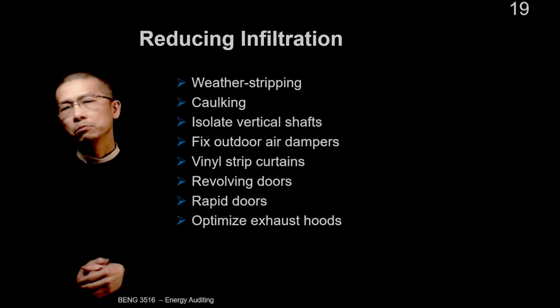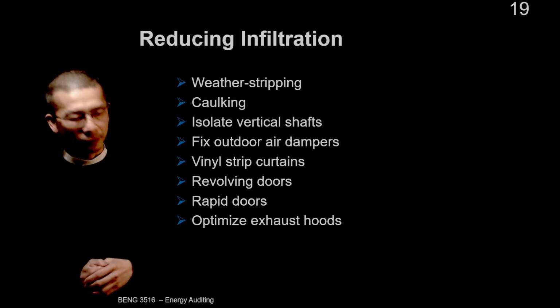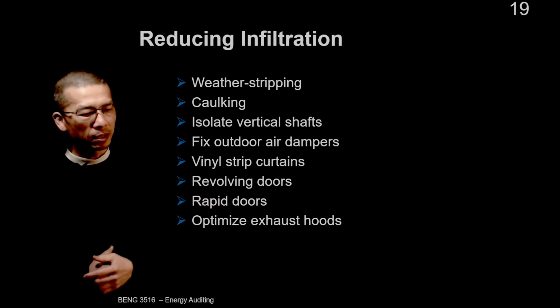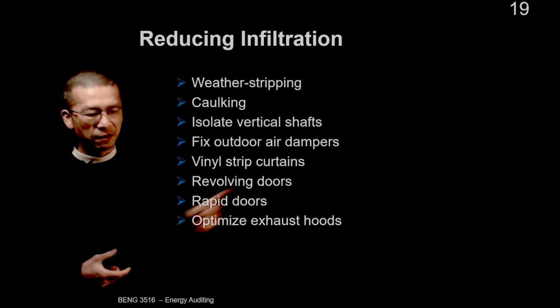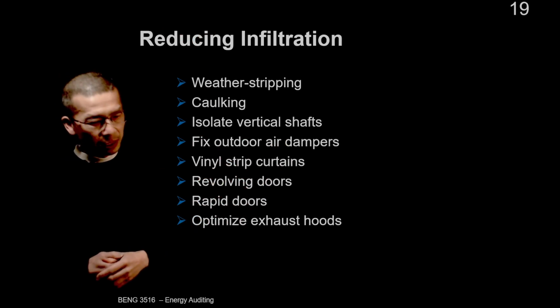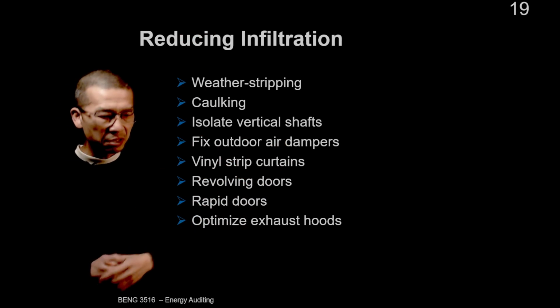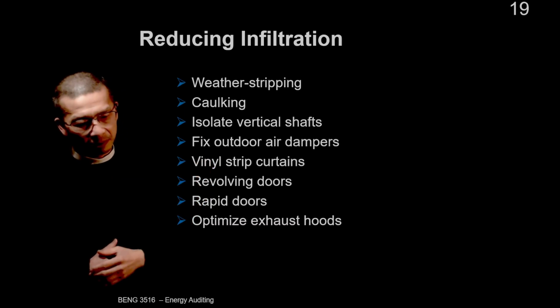All right, so here are some of the strategies that we can use to reduce infiltration. Weather stripping, caulking, vertical shafts, that's for the high-rise buildings, fixed outdoor air dampers, checking whether the dampers are functioning properly or not.